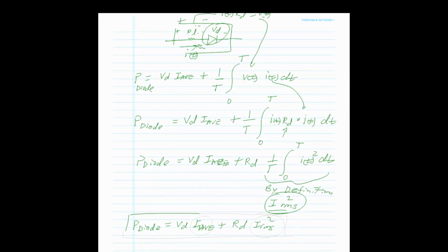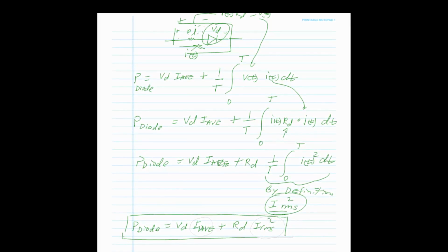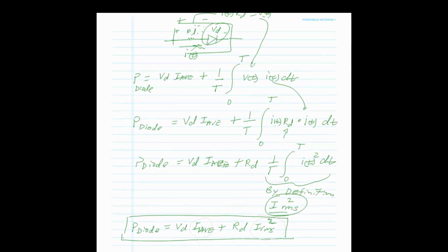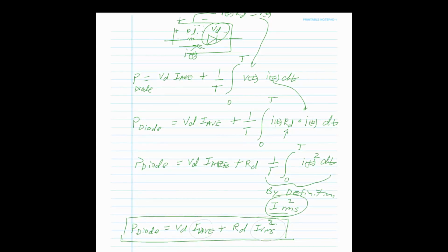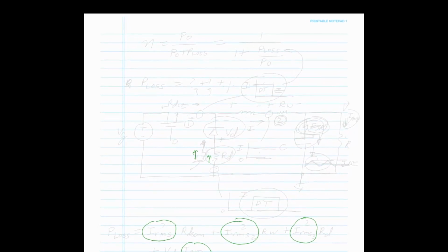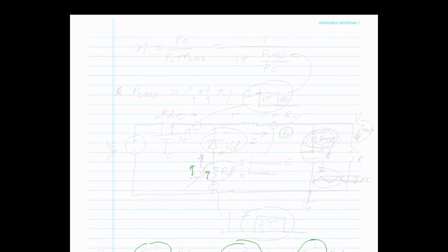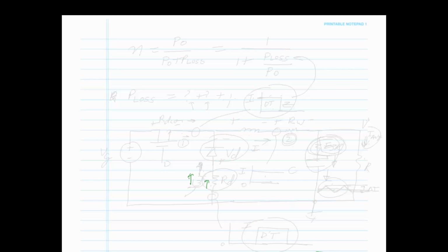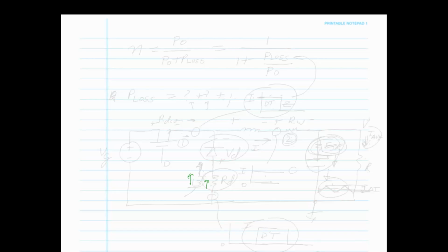That's my total power dissipation in any of the devices. So in other words, all we have to do is give me the wave shapes. What's the average current? What's the RMS current of all wave shapes that you'll ever see in switchers? And I put it in table form. So all I have to do is look at what the waveform looks like.